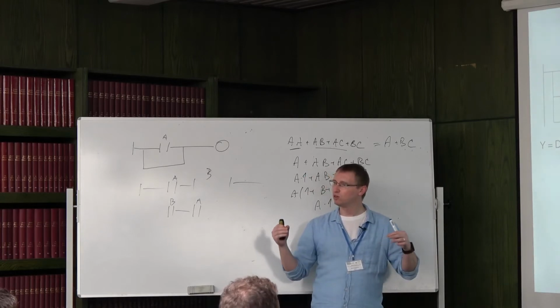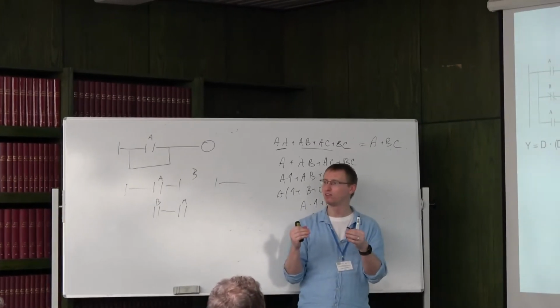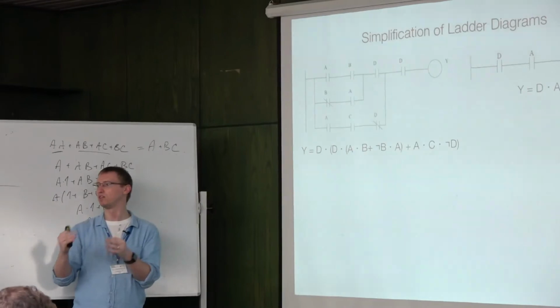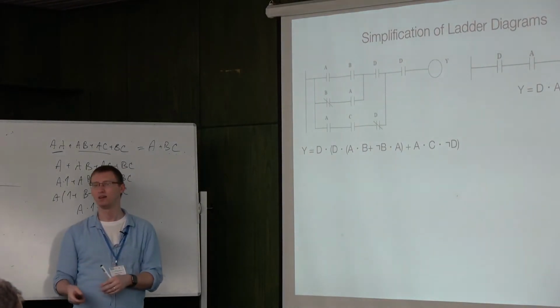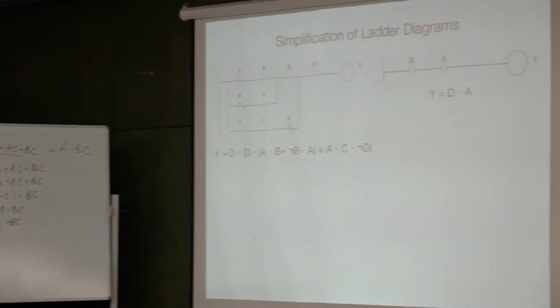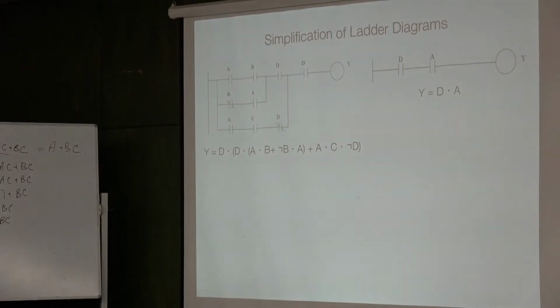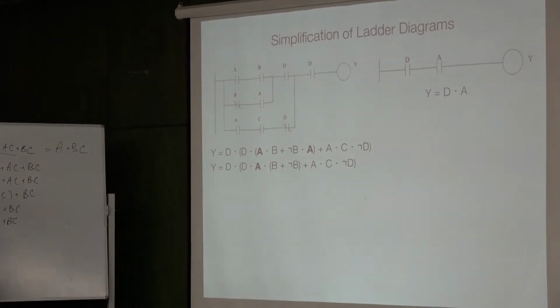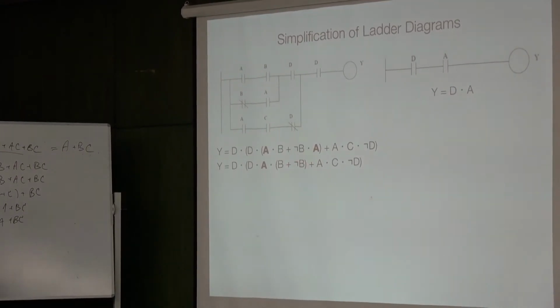And these are what might help us to actually simplify this expression to this form. And here I'm going to do it completely manually, but that's what I'm advocating for. Let's write a software tool which does it automatically. I see a huge opportunity in that, okay? So you might look here, say, on the parentheses here, let's take a common. So A is here. B plus not B, so light is on or light is off. That's always satisfied. That's times 1. Times 1 we can just simplify to the left-hand operand.